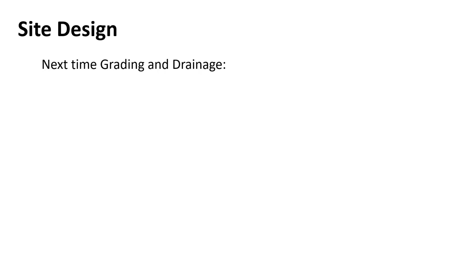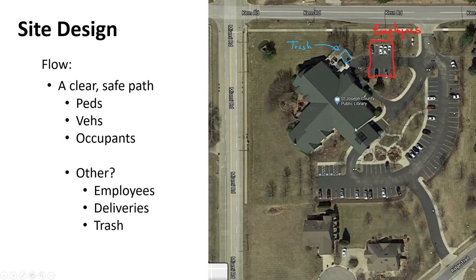And I think it's kind of fun, honestly. It's always like a puzzle, right? It's like doing Sudoku. Engineering's a lot like that. You know what the elevation of the floor is here in the building, and you have to get people out to the parking lot, which is probably a lower elevation, but it can't be too steep, yet it has to be steep enough to keep water moving. And you've got to show enough elevations to show everybody how to build it. So it's kind of interesting, and it's kind of involved. You can take quite a bit of time to do a good job on those site plans.